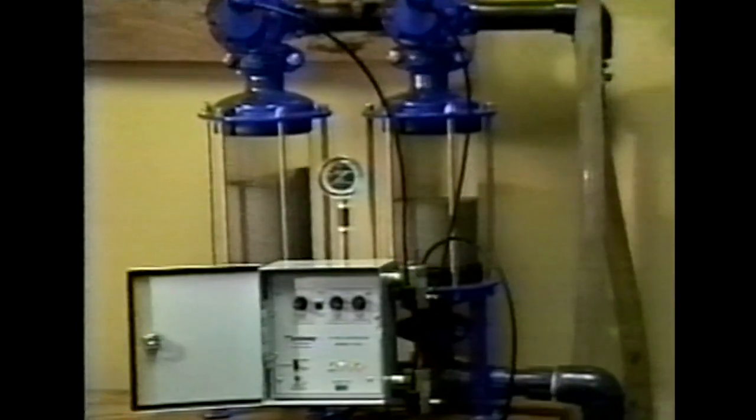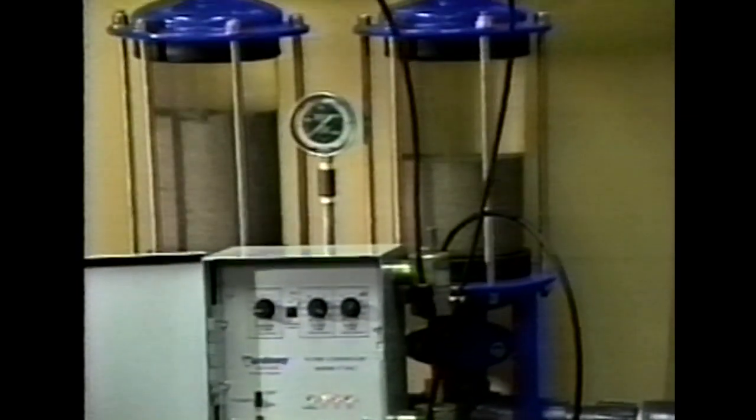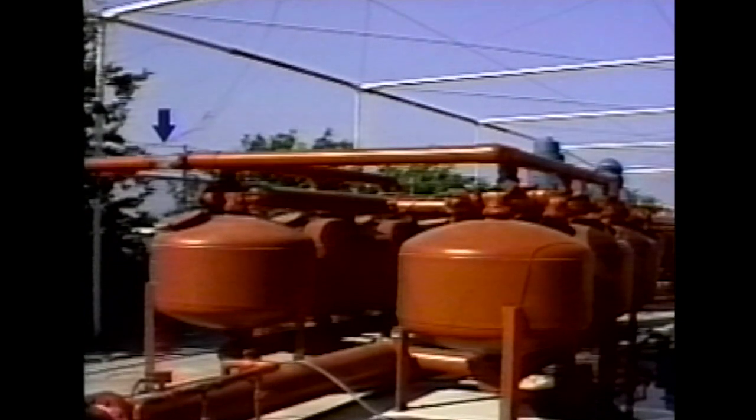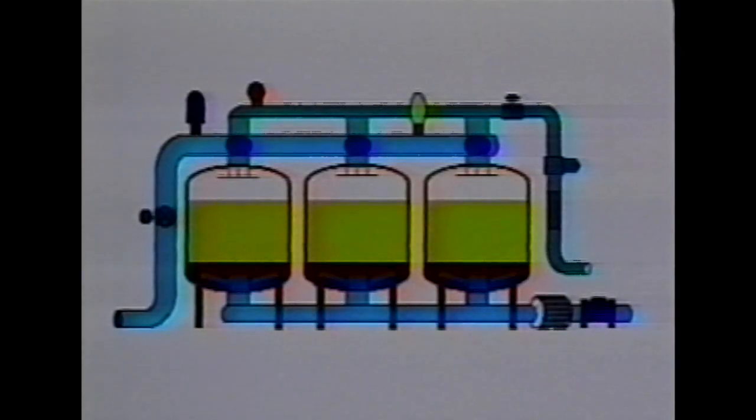Sight glasses are used so that drip system operators can see the quality of the media tank backflush water. The backflushing should continue until the backflush water looks clean. The sight glasses must be conveniently placed and easy to see.